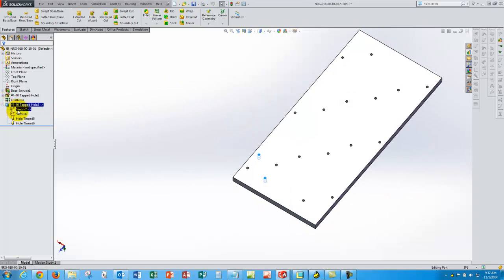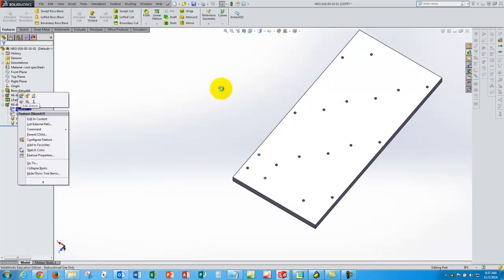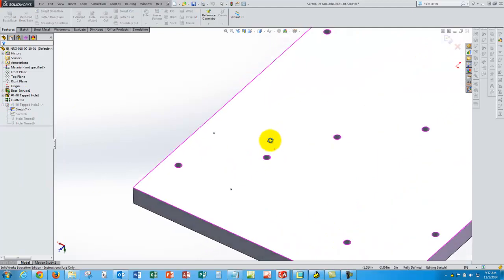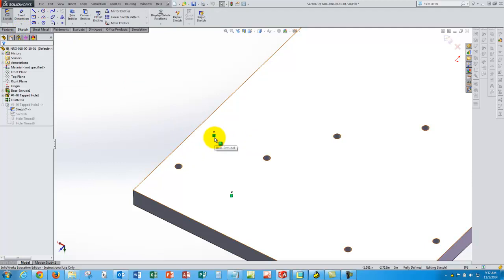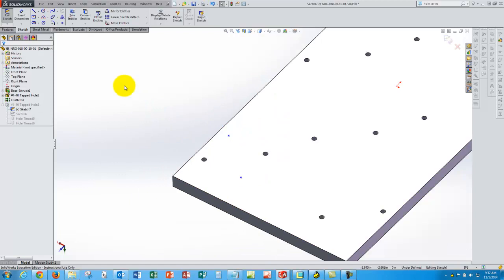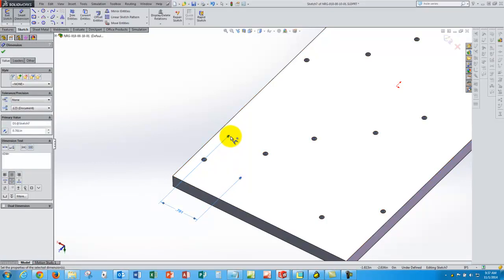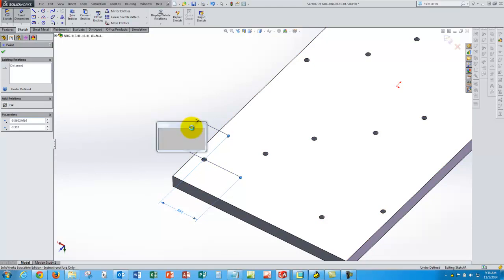So I'm going to go inside the sketch, edit it, and I'm going to get rid of these constraints that are based on the resistor, so they're free floating now. And I want to put some dimensions on there, and they're not going to move because I'm just going to use the dimensions where they're sitting. So right now they're sitting exactly where they need to be, and these are the dimensions that they need to be located. And I'll do the other dimension in the other direction. And just type those in, or let those stay like they are.